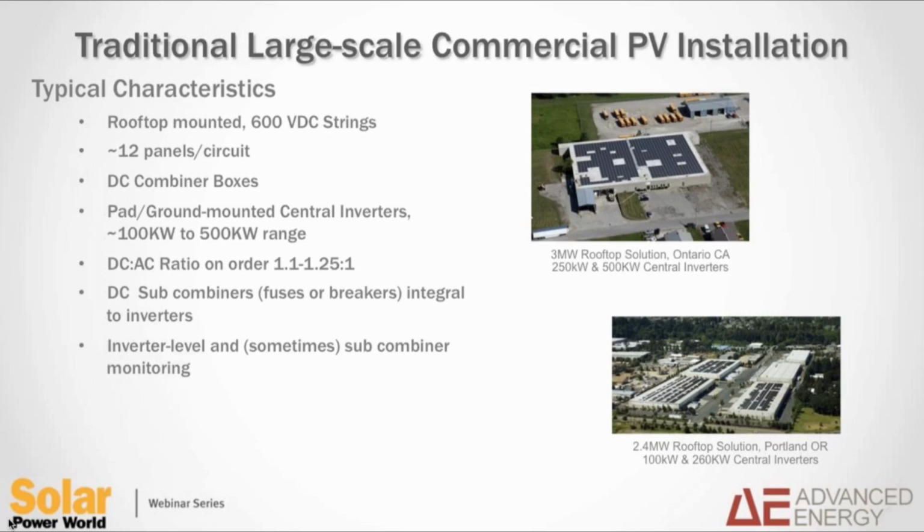And for larger installations, inverters would typically have maybe sub-combiners of fuses or breakers. We put some kind of monitoring in there, either at the inverter level or revenue grade monitoring, for example, and we may even monitor the sub-combiner inputs. There are a lot of installations that may not fit this exact model, but I think this is a good typical characterization that we can build on for this presentation.